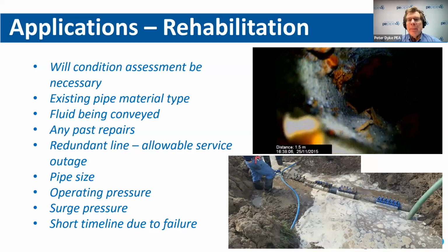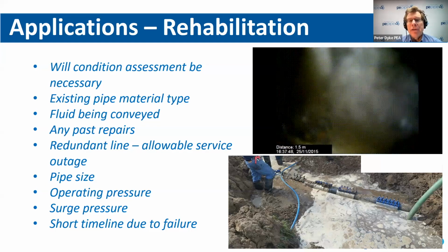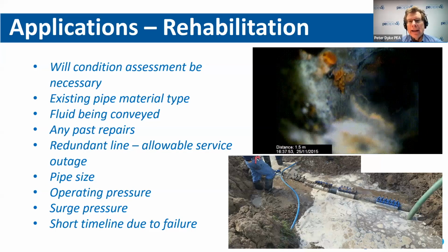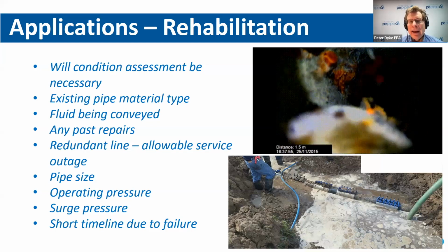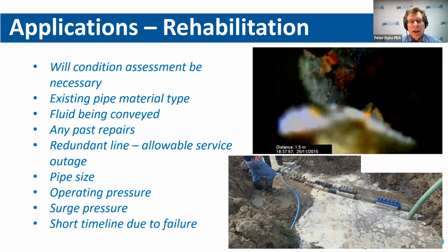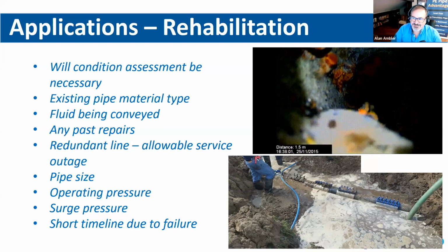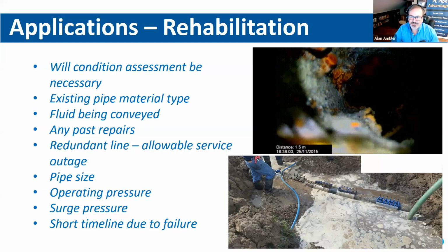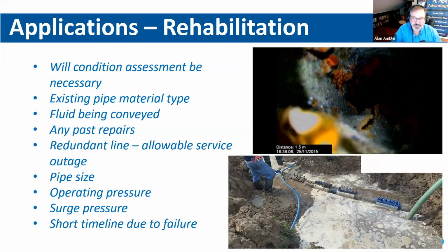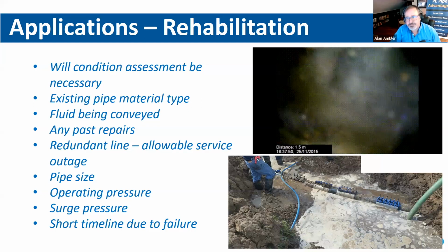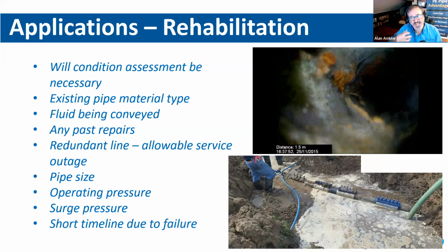Hey, so with that bottom image, I love that image. You know, oftentimes we're asked, how do you pipe burst a line segment, Alan, when it's got that many repair clamps on it? We get this question a lot. How does that happen? You don't, Pete. It just becomes an excavation in many instances, and that becomes your machine pit. Sometimes you can burst through a lower quality repair clamp, and sometimes it'll just drag it through as you go through.